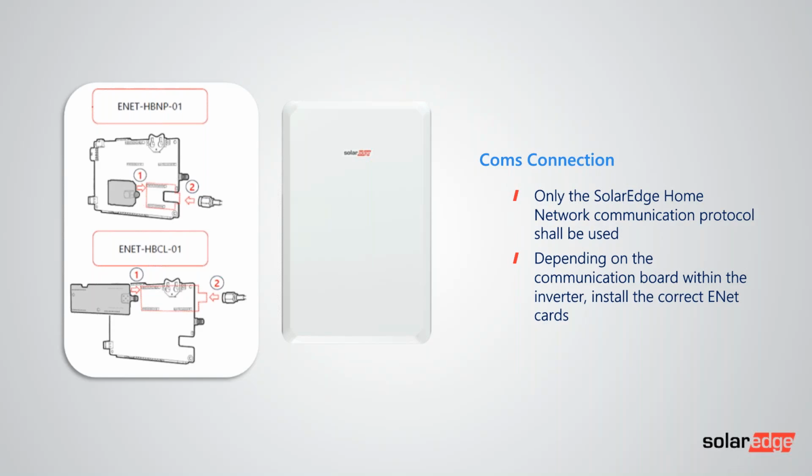What you cannot do is put the big one onto the board which has the two ports on it. The reason being is that it wasn't designed for it, and the battery terminal is much larger and it can cause communication issues with that board. Now, this is only really a problem for existing installs which were put in over two years ago. All current inverters since then have the dual boards, so they'll take the small EnergyNet cards. So all new installs, this isn't going to be an issue at all. If you're going to add a battery onto an existing install, the advice is basically just to take both sets of cards with you, and that way you know to install the appropriate one.